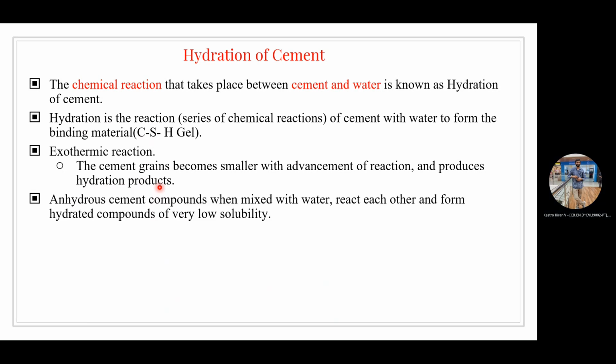With this exothermic reaction, whatever anhydrous cement compounds are available in the cement matrix, when they are mixed with water, they react with each other and form compounds which are called hydrated compounds. And remember, these hydrated compounds are very low soluble materials.